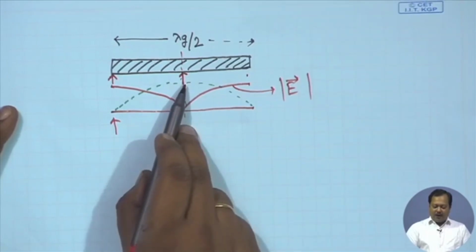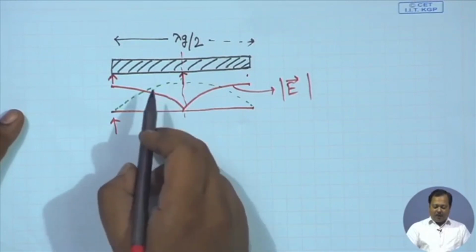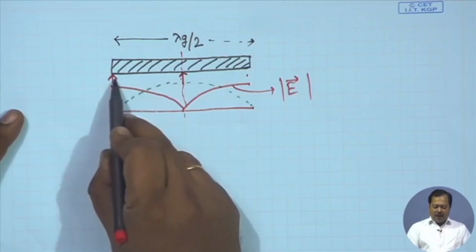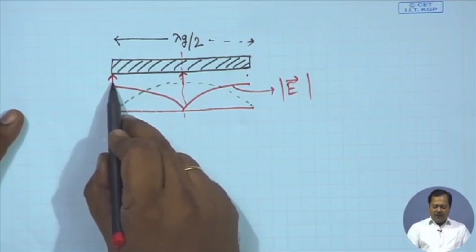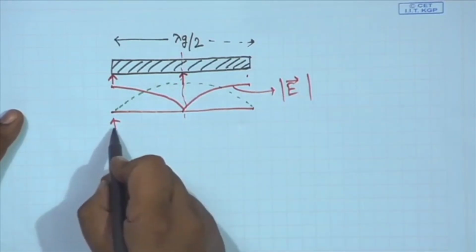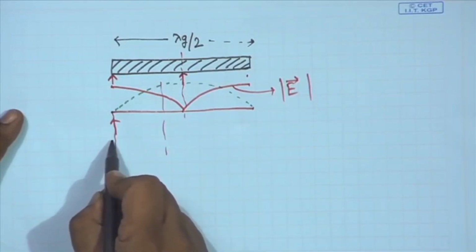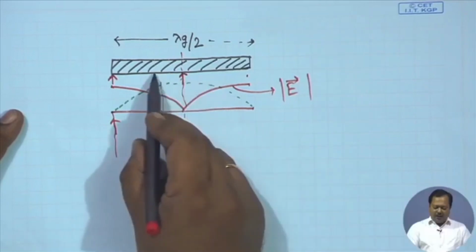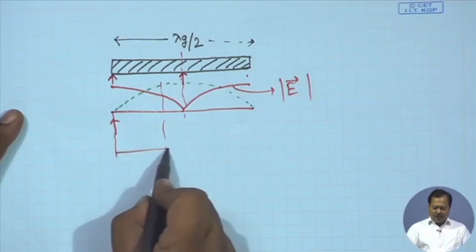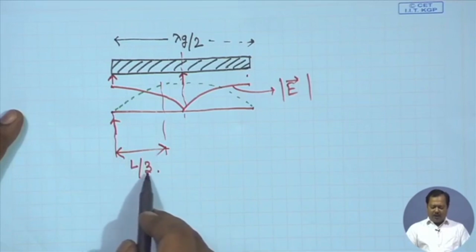For microwave circuits, mostly we use a 50 ohm system. So, for impedance matching, the feed point will be somewhere in between the z equal to infinity and z equal to 0 planes, and the thumb rule is that you consider 1/3 length from the left hand side. So, if the length of this resonator is L, the approximate feed position from the left hand side is L by 3.